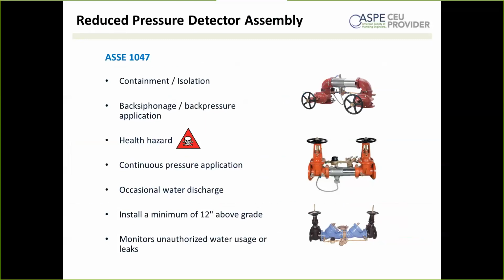Typically, they have another RPZ and a meter in the bypass. The only difference is, you might want to make sure that you're capturing the discharge both from the RPZ and the bypass and the main valve. But as far as the actual inner workings, it's exactly the same.